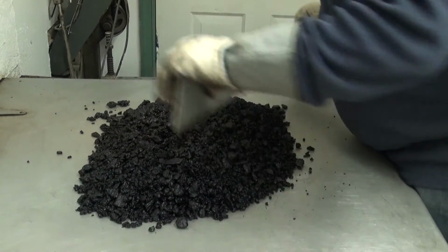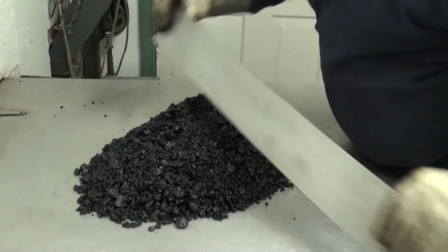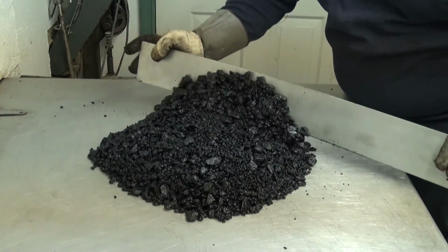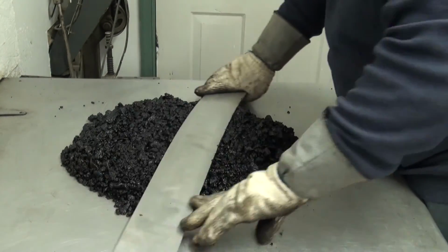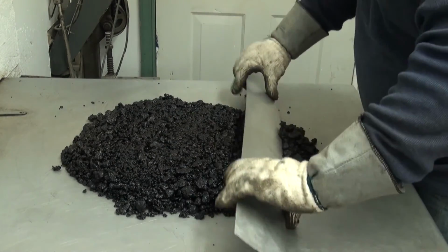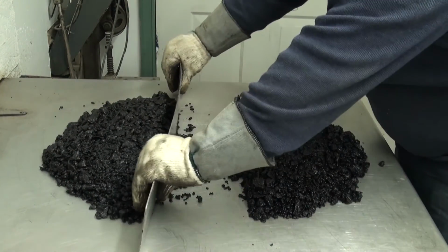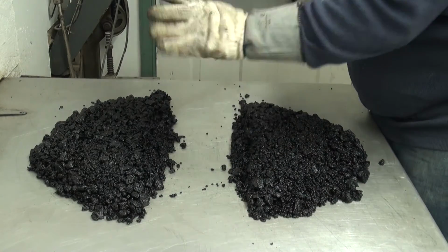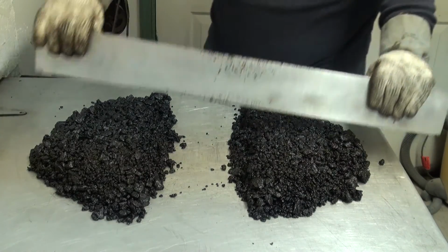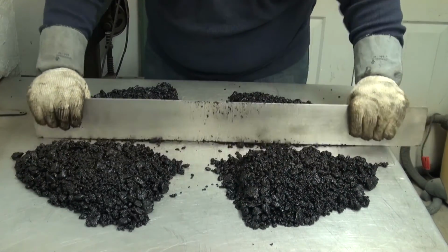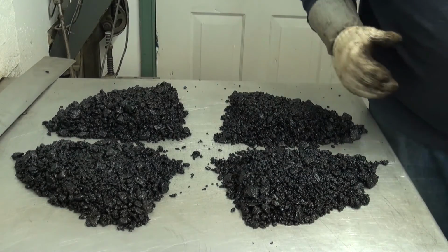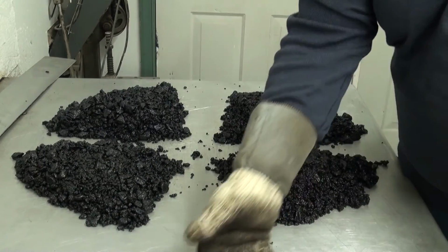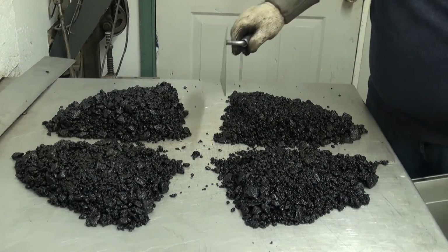As you can see, just looking at this mix, it's a base mix, the large aggregate it's got in it. You can tell he's, again, mixing his material up, setting it on top of the pile, creating that conical pile. But it's important here before he begins to divide it, he's leveling it off, he wants to look at it and make sure it's homogeneous. Make sure he doesn't have any segregation, because these mixes are much easier to segregate, and this is where you can really affect your test results if you don't take time to do a good job of mixing your sample up before you start quartering it.